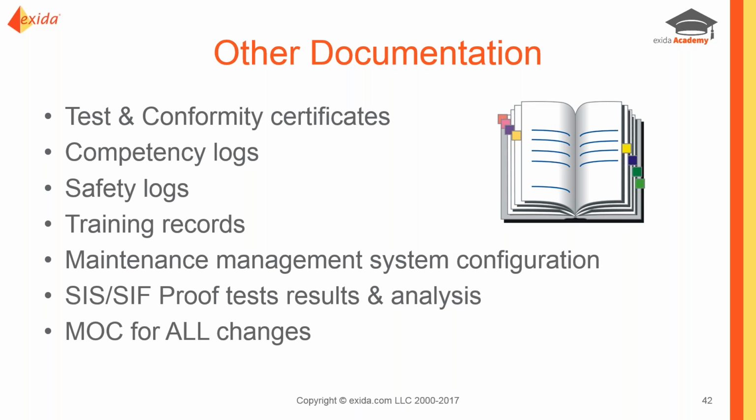How do we configure our maintenance management system in order to make sure that we trigger these proof test activities when they should occur? And then, of course, what are the proof tests and what are the results of those proof tests? How are we going to log those over a period of time? And what kind of analysis are we going to do on that data to demonstrate to ourselves that the devices that we've chosen, the methodologies that we're using to ensure the health of these components of a safety instrumented function are performing to the reliability criteria that we believe they have.